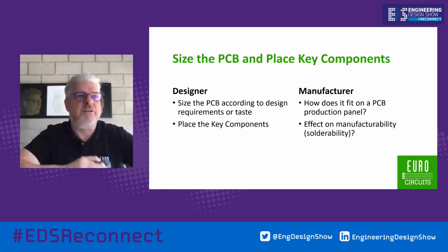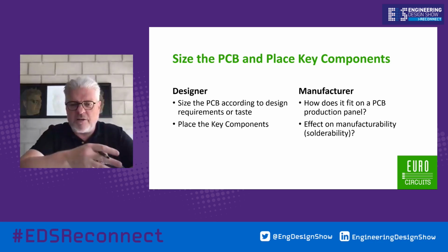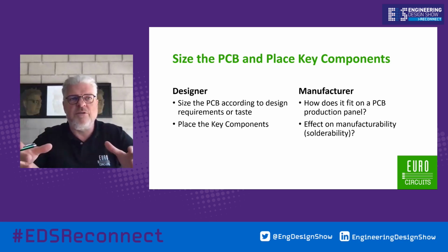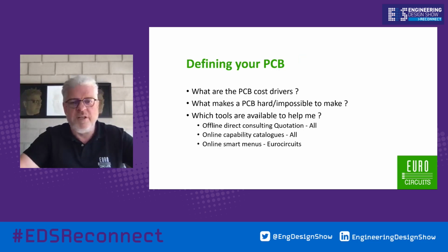And also here, there is a difference between the designer and the manufacturer for sizing, because you need to size the PCB according to the application you're building. But the manufacturer looks at how efficient the PCB is on a production panel. And for a big series, this might be an important parameter. So definitely also something to take into consideration.